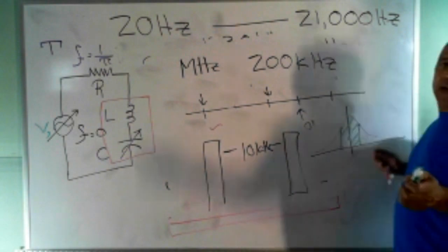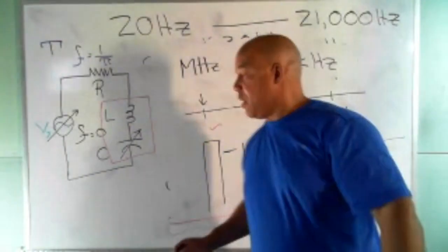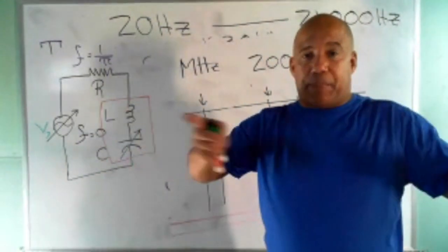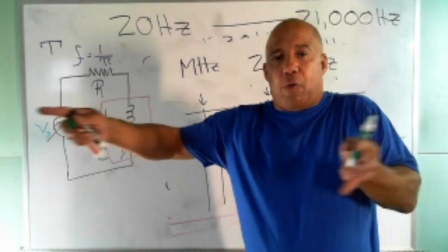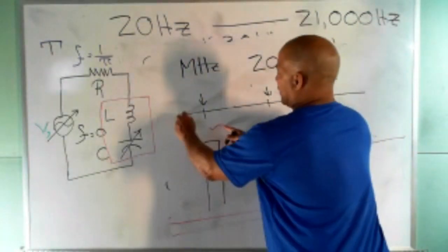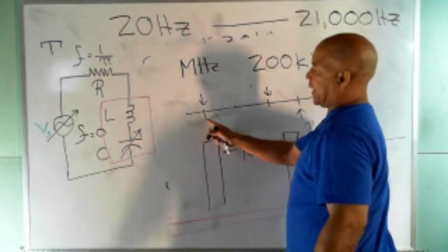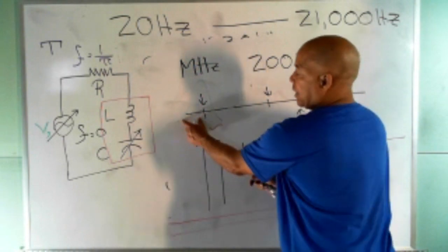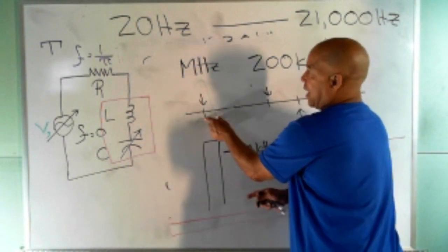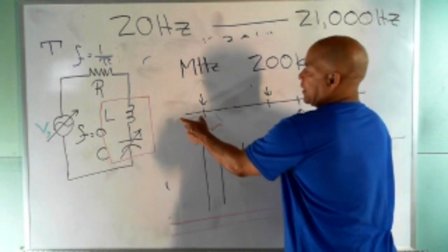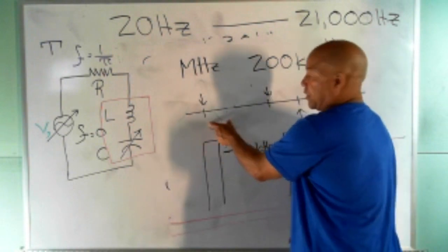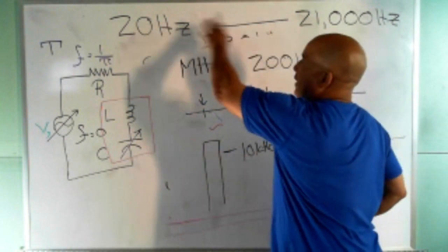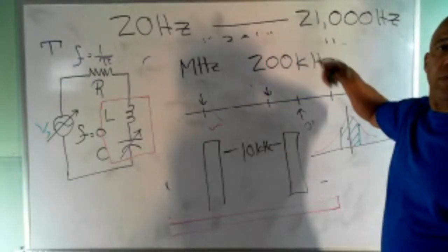When you tune the radio, when you go from one station to another, what you're doing is you're changing the resonant frequency. By changing the capacitance, you're moving that whole band up and down. You can move it up. If this is your resonant frequency, you pick it up. That center frequency FR, and then 5 kilohertz this way, 5 kilohertz that way if it's AM. If it's FM, it's 100 kilohertz to the left and 100 kilohertz to the right. The bandwidth is much wider. And so you get all that frequency for human hearing through that bandwidth.